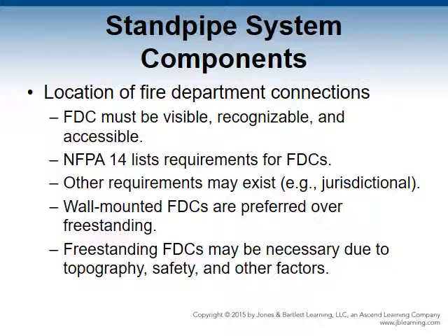Other requirements. Many jurisdictions require more than one FDC on buildings over 5 stories. High-rises must have 2 or more remotely located connections per zone. Multiple FDCs ensure continued access for the fire department in the event of damage, blockage, etc.